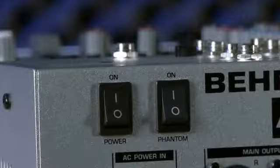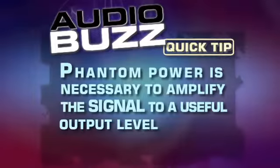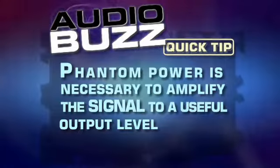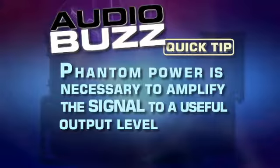They require a power source either from phantom power or from a small battery. Phantom power is available on most professional cameras and audio mixers. Power to a microphone is needed to establish the capacitor plate voltage, and it's also necessary to amplify the signal to a useful output level.